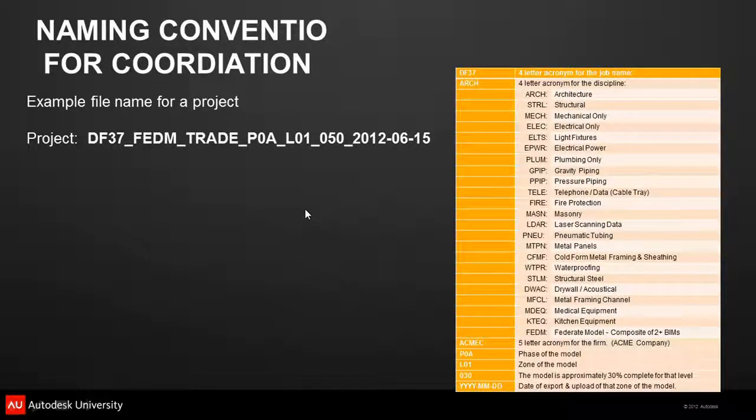When we do plumbing jobs, we have a very well-defined naming convention for the files we export out, and this has helped us. We use Navisworks Manage to run coordination, and we have a naming definition that defines the project, the type of model it is, and we have an outline that shows all the different disciplines, and then the levels, and then the end of it is a specific naming convention that says the percentage complete of that model.